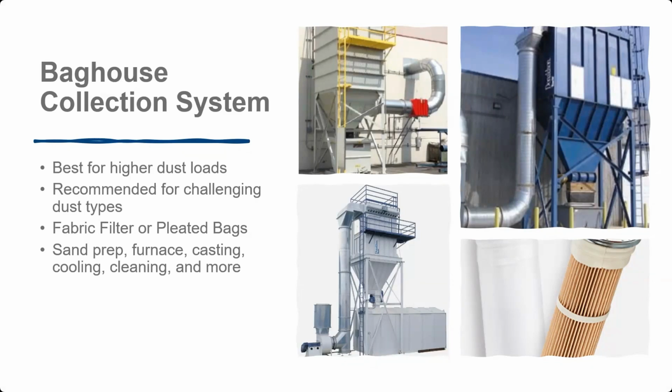The pulse jet cleans during operation, and you can make them a lot smaller and more compact, so they take up a lower footprint. I would guess 80% or more of the dust collectors in your facility are pulse jet dust collectors, so we'll be talking about these quite a bit today. They typically use a fabric bag in a cage, or they can also use pleated filters.